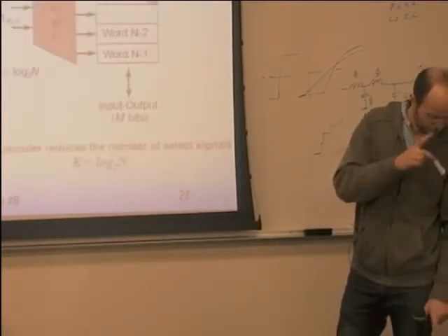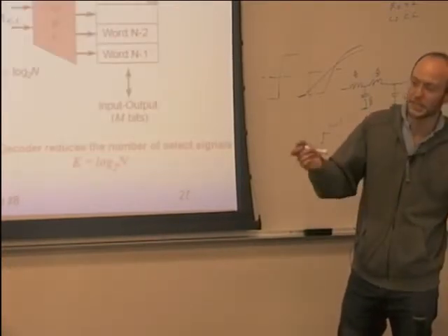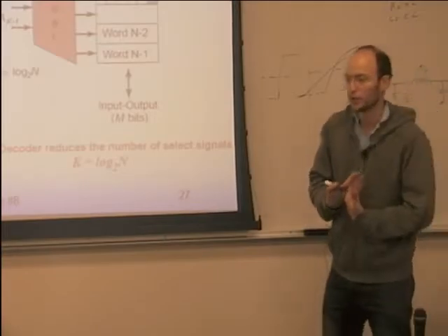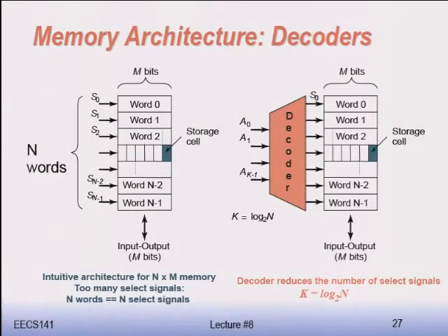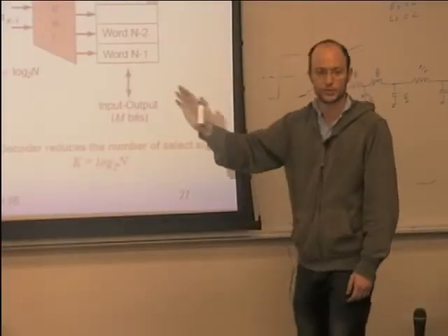So now, you have n bits coming in, but you have 2 to the n wires coming out, because each row and each column is one wire. Imagine for each row and each column there is a transistor that you need to turn on the gate of if you want to select that row. This is pretty much what it is. Are you guys following?